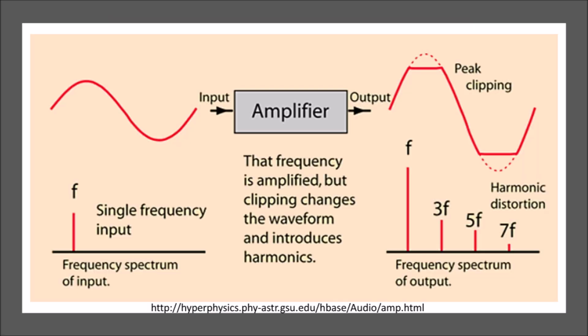Even though we're not trying to increase the amplitude of that signal or change any of the frequency content, there are still some imperfections in the circuit, whether it be the saturation of the transformers or what the tube amplifier portion's doing. There is something being added, some slight amount of harmonic content being generated that fills in those sonic gaps that we feel is empty otherwise, or especially in the digital age, that we feel is not being replicated properly with software or by cleanly recording something.